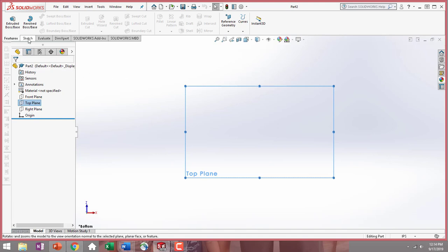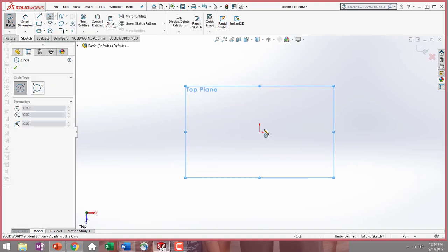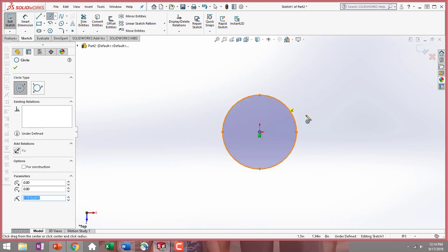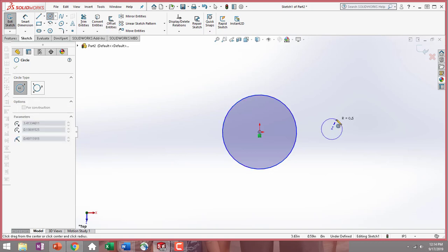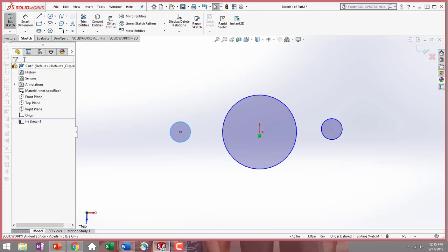Now for this one, I'm going to start with my inner circles. So you go ahead and open a sketch, select the circle icon, and I'm going to have my circle be connected to my origin. So select it down. Since I already have the circle sketch open, I'm going to create 2 more. Since this part is going to be extruded all the same length, our sketch can be all done in one sketch. If we needed multiple extrudes at different depths for this, we would have to create multiple sketches. You cannot create different depth extrudes in the same sketch.